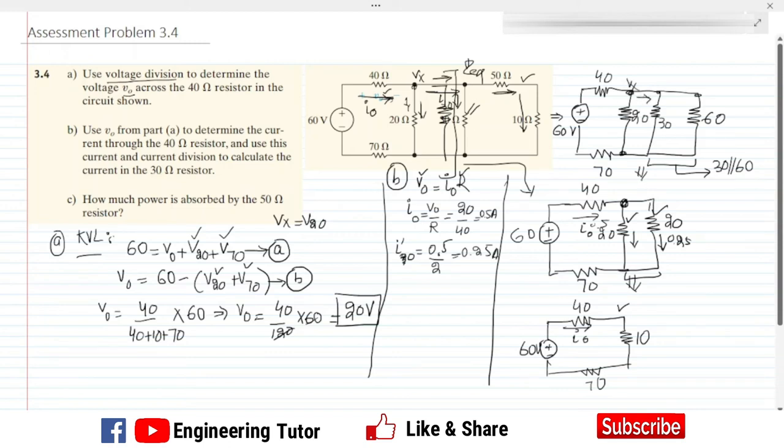We can see now this is the equivalent resistance of this 30 and 60. So now we can find out the value which is flowing through this I30 by using this I0 prime. In order to find out the value of I30 here, we know that these two resistors are in parallel. So 60 divided by 30 plus 60, whole multiplied by the I0 prime, which was 0.25 amps.